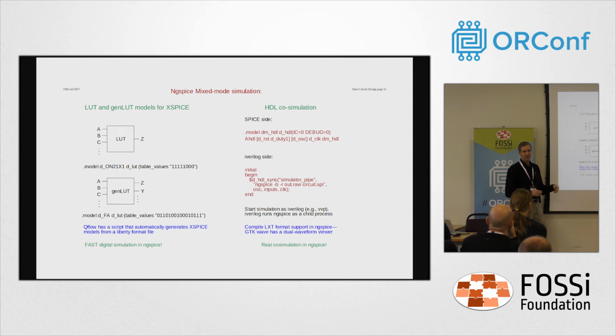For the others, you may have a few things with 2 outputs. I created another one called genlut for a general lookup table, and then you can do multiple outputs that way, so you can catch the other few odd cases like full adders, half adders, and so forth. Latches and flip-flops, XSpice already had pretty good general purpose models, so I didn't need to reinvent the wheel there.